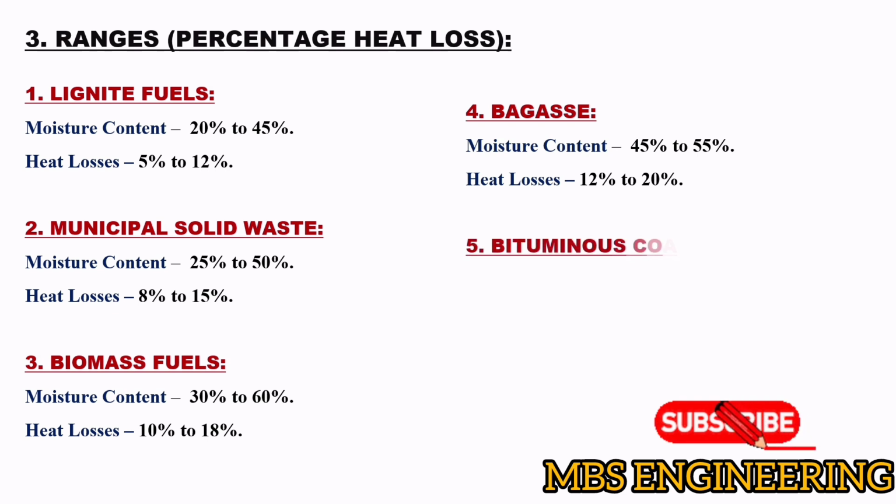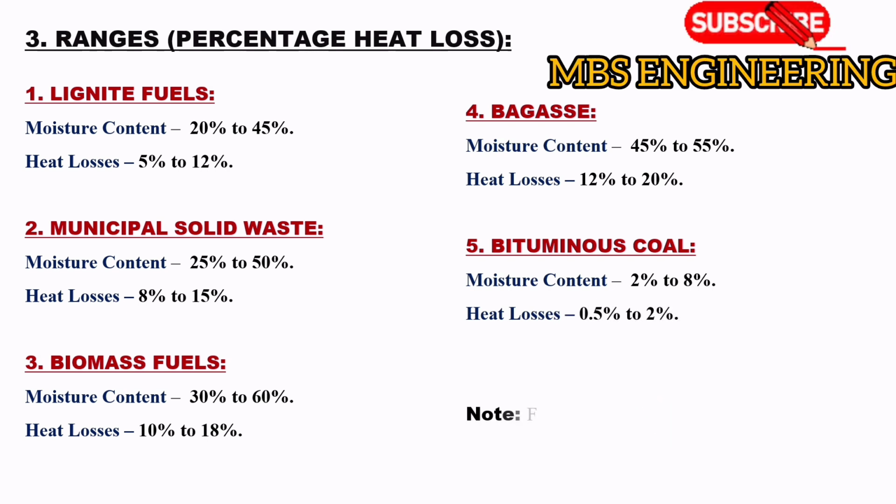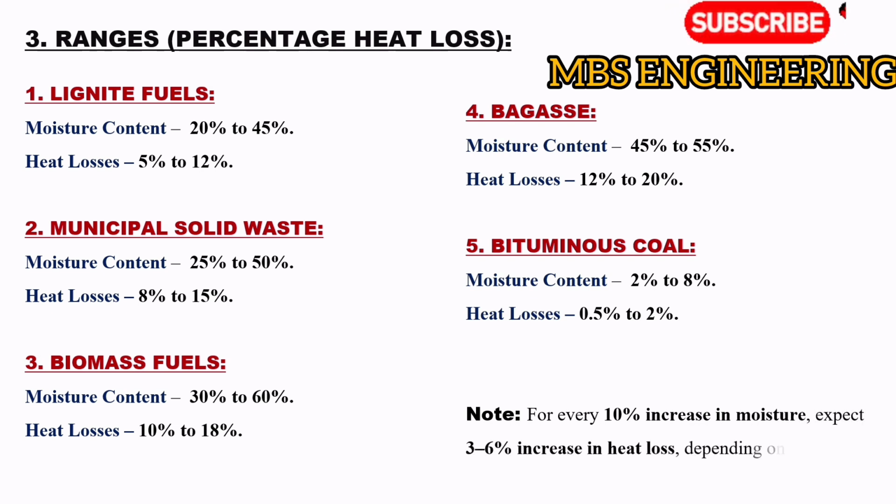Next, in bituminous coal, its percentage of the moisture content ranges from 2% to 8%. Its percentage of the heat losses ranges from 0.5% to 2%. Please note that for every 10% increase in moisture, expect a 3 to 6% increase in heat loss, depending on the flue gas temperature and fuel gross calorific value.